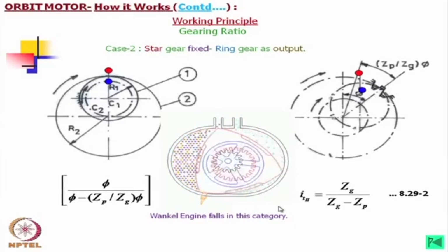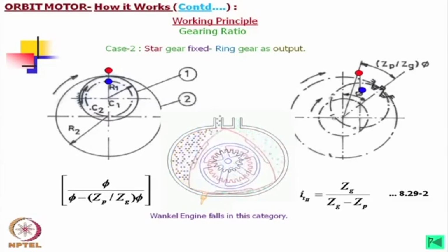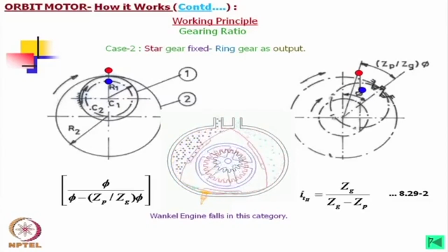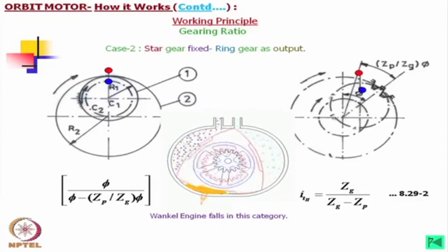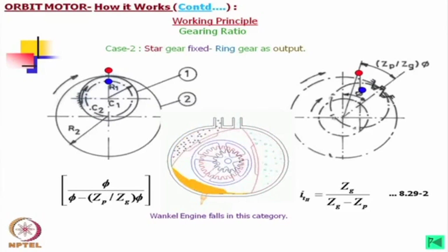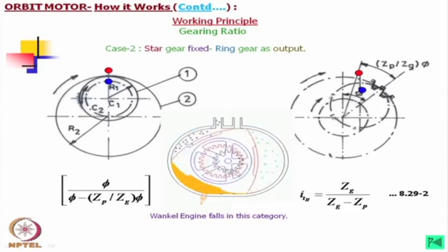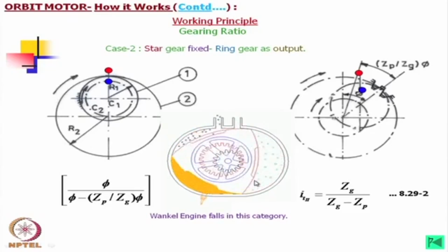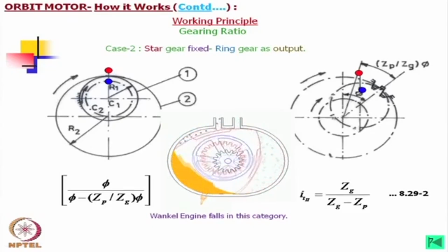This is possible if we cut the material by the opposite cutter. I have told you why we generate the envelope using that cutter as hollow and solid. If we make this cutter hollow, then the inner member will be the envelope, and the envelope will have one lobe more than the outer member. The Wankel engine is generated in this way.